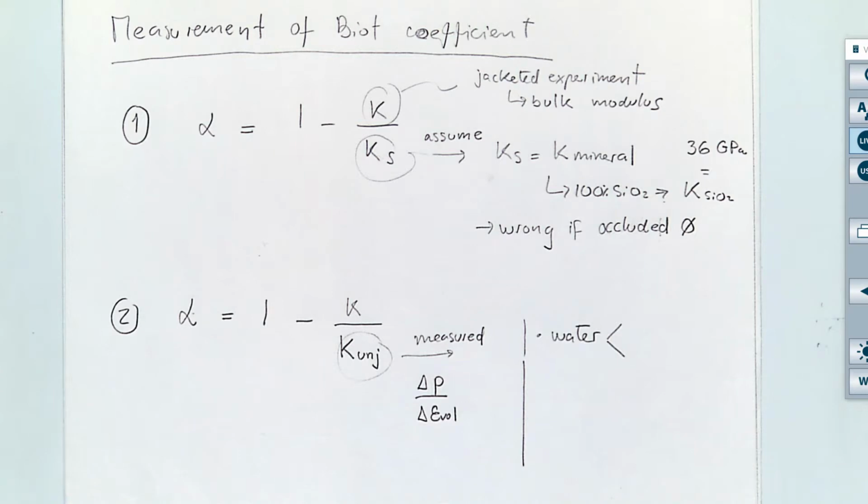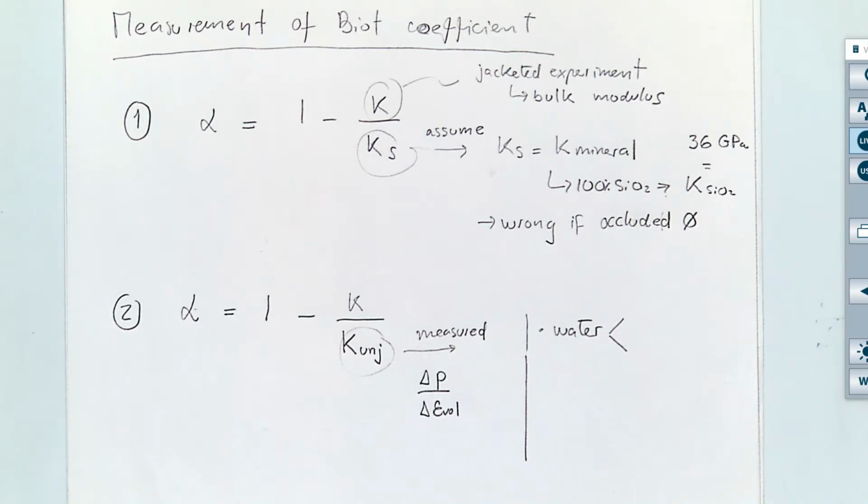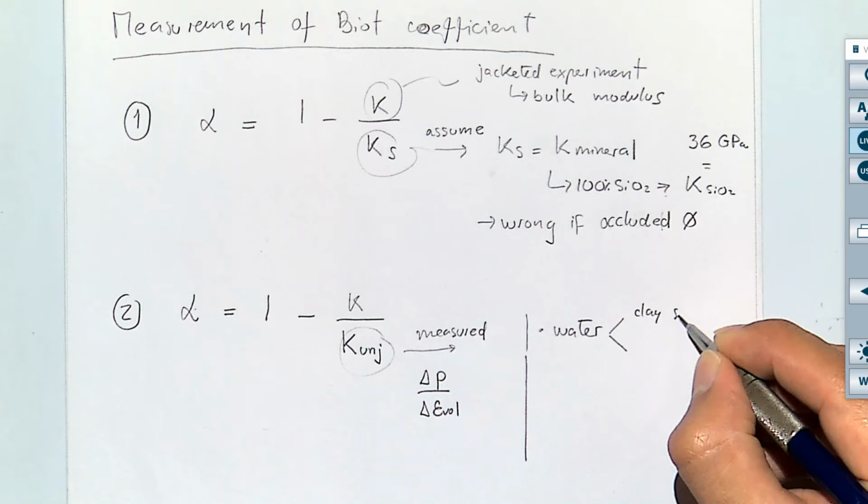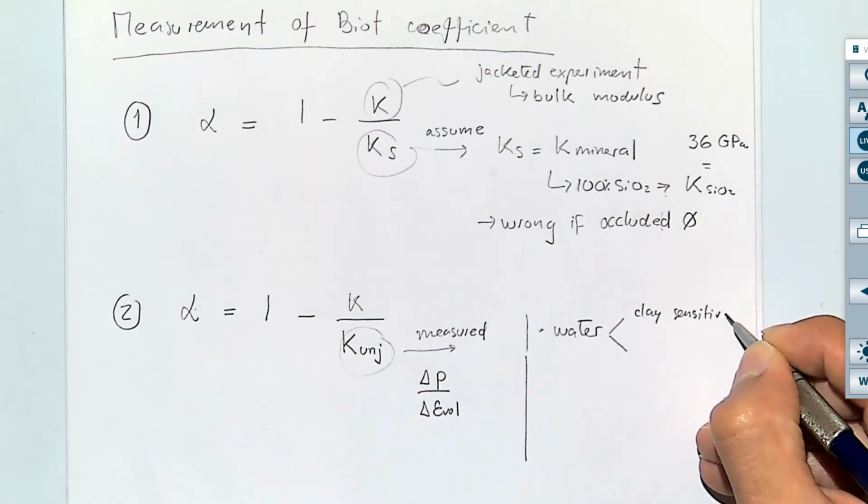Let's say we use fresh water. What happens when you expose a shale to fresh water? It can swell. Clays don't like fresh water. They will hydrate and they will swell. So this is not good. And for any clay sensitive rock, this is not a good idea.